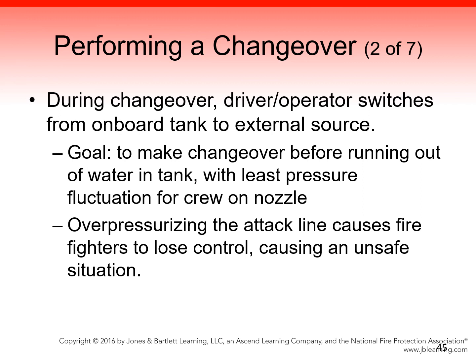The goal with this task is simple: to make the changeover prior to running out of water in the tank with the least amount of pressure fluctuation for the firefighting crew on the nozzle. Overpressurizing the attack lines can cause firefighters to lose control of the hand lines, causing an unsafe situation.